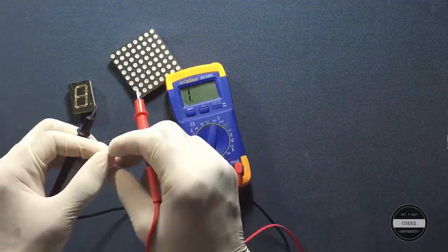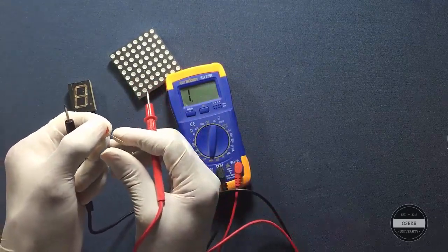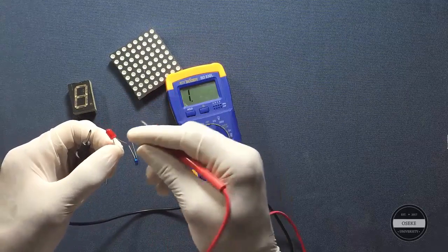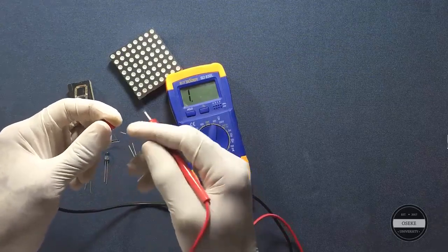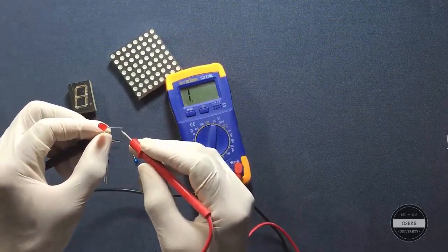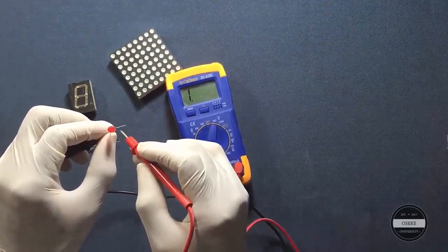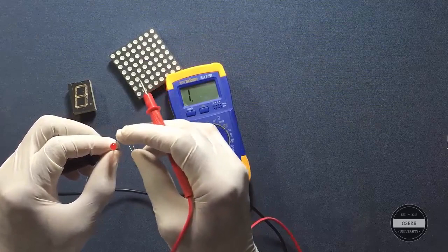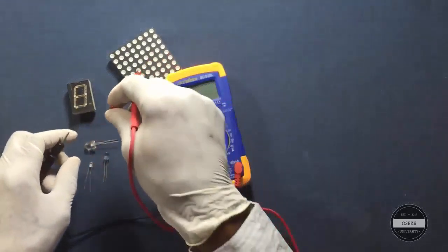Start with this one. We will not test everything for the sake of time. To test, it's very simple. First of all, you spread the legs of the LED a little bit. Don't spread them too aggressively, or otherwise you can break the leg. I already know this is my negative and this is my positive, based on this being the longest one. So I put the black lead on the negative, and as soon as I put the red on the positive, I expect this LED to light up. All right, let's do that now. See, it lights up. This means the LED works, and it is clear for takeoff. It is clear to be used in an actual circuit.